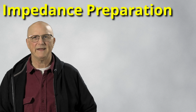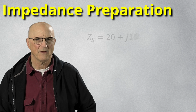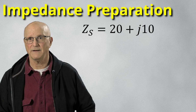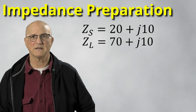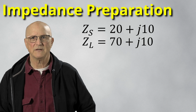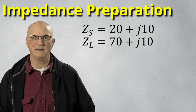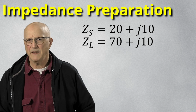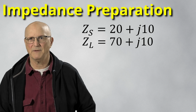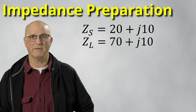I'm going to begin by getting our impedances ready for the exercise. In this example, we have a source impedance of 20 plus J10 and a load impedance of 70 plus J10. The first thing that we have to do is normalize each of these. This requires some sort of system impedance. For impedance matching, the value that I choose for this really doesn't matter because in the end, I'm going to be undoing this convention with the same number.